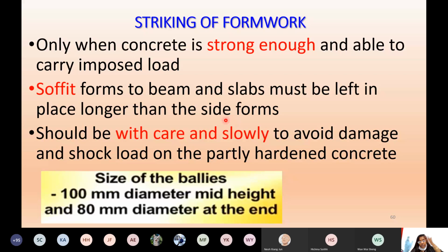Yeah, we need to remove the sides first, then go for the bottom. That's what it says. You need to leave the bottommost longer. I will show you later when we go for scaffolding; we will teach all these things clearly with pictures. But when you remove formwork, go for the sides first and then the bottom. Leave the bottom for another 1 week or 10 days.